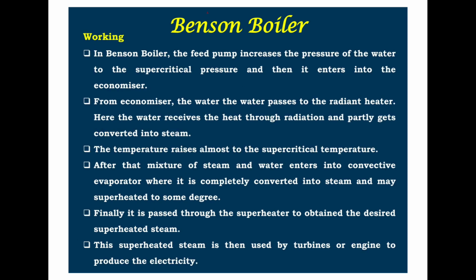The working principle of the Benson boiler. In Benson boilers, the feed pump increases the pressure of the water to the supercritical pressure and then it enters the economizer. From the economizer, the water passes to the radiant heater.